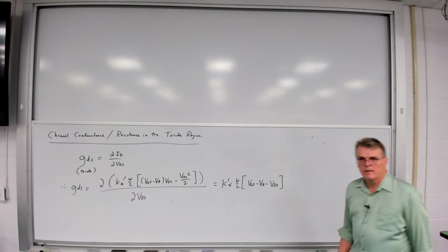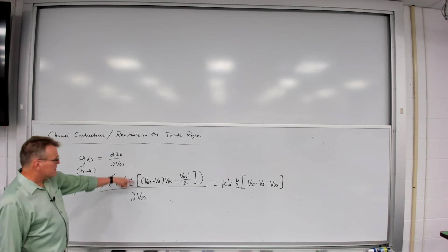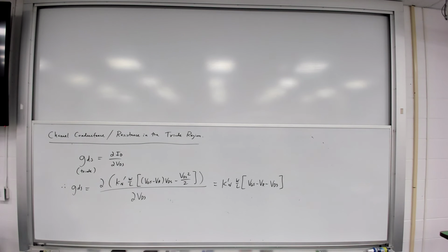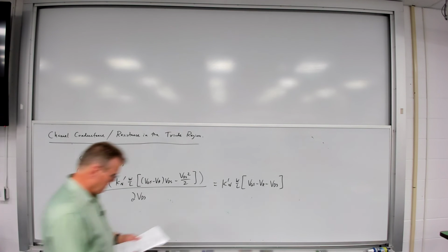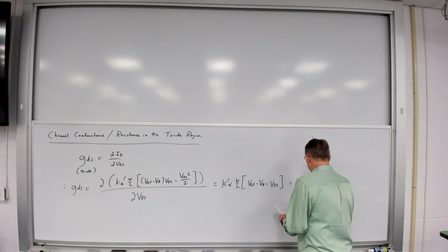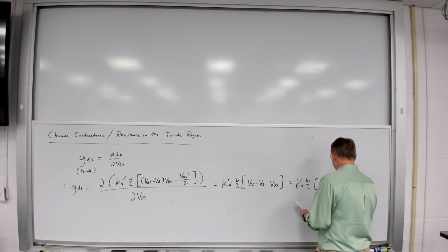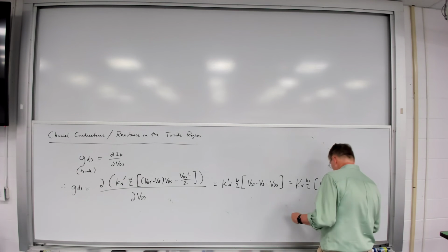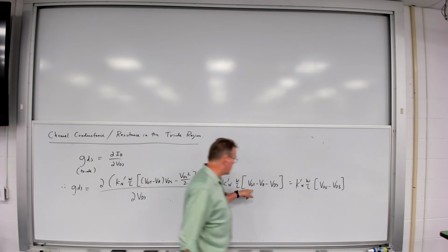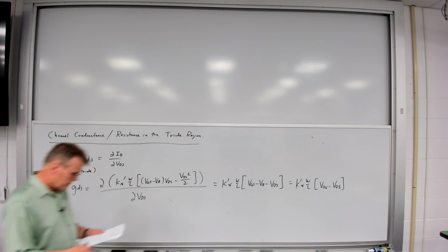I'll get this. If you look at it, it's actually pretty straightforward because I can break this into two parts, take the derivative here and the derivative there, and it very easily becomes that. So you can see for yourself, it's a simple derivative. Or I can say this is equal to K prime N W over L times VOV minus VDS. In this case, I'm using the overdrive voltage definition the book uses. All right?